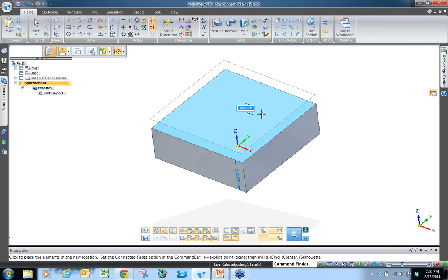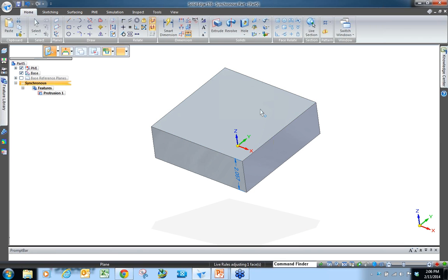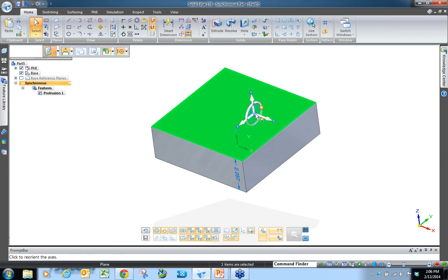If I want to go ahead and key in a specific measurement, how far I want to move it up, I can just use the key-in function, you'll see the white box in there. I can go ahead and say I want to go up half an inch, and it'll readjust. Also, which is automatically applied, I have a vertical dimension here, and it's showing 2.057.